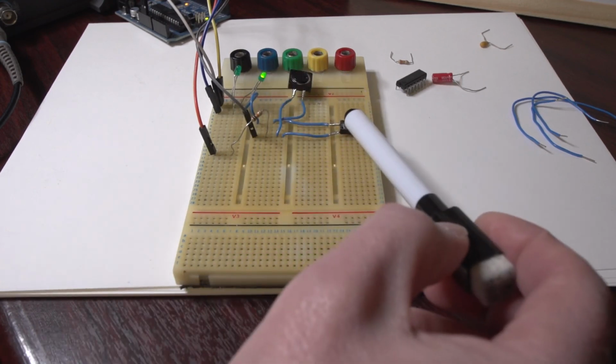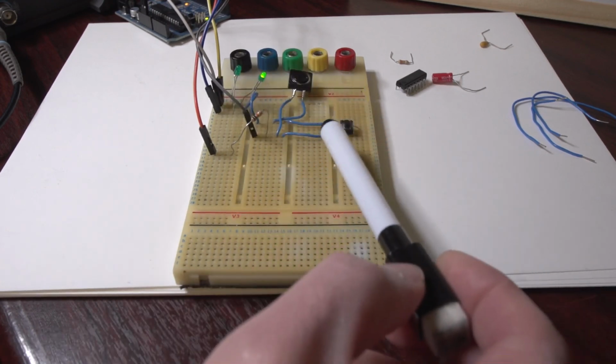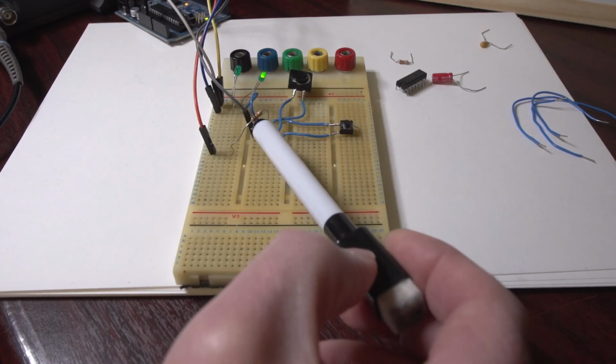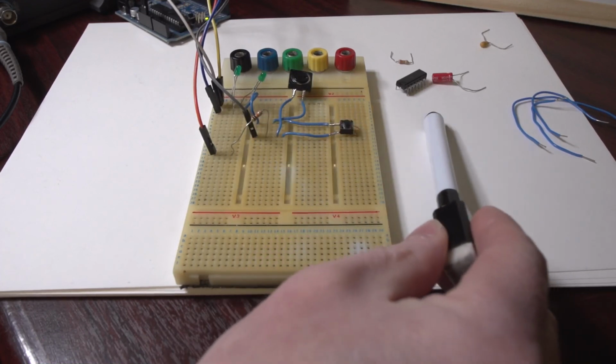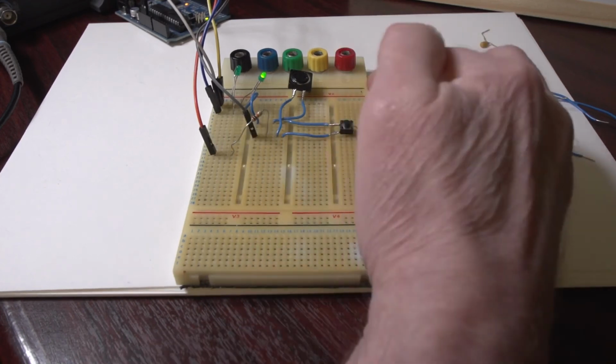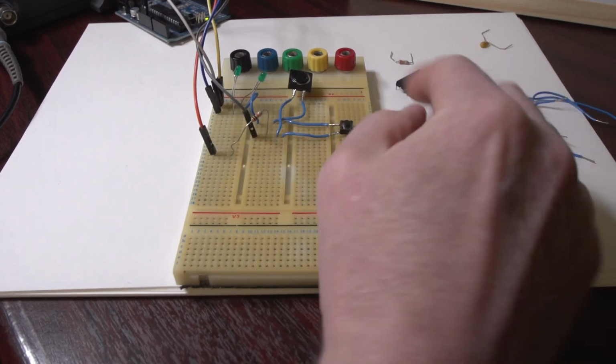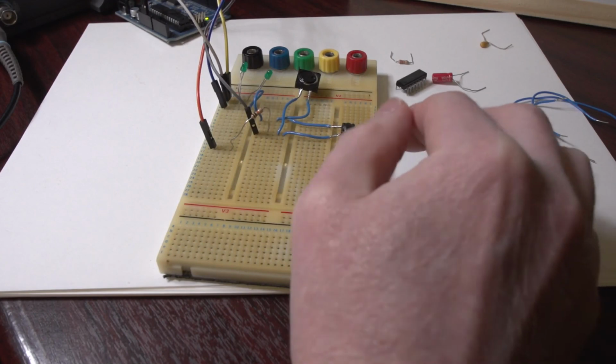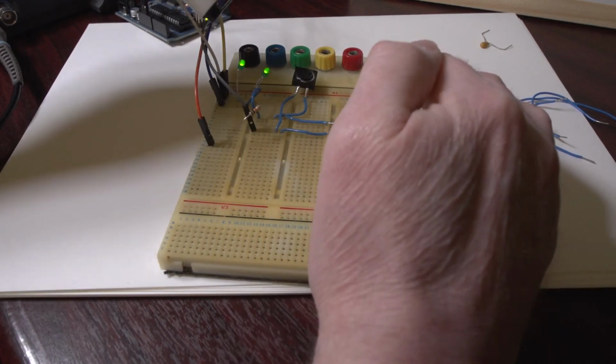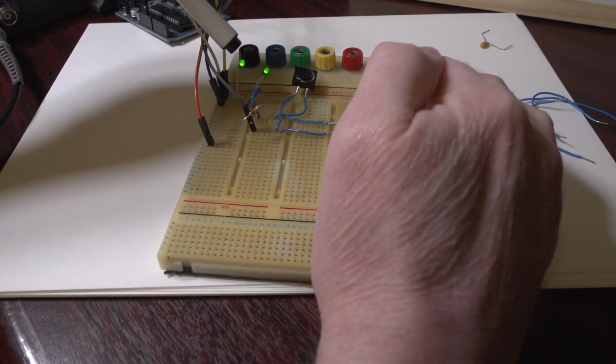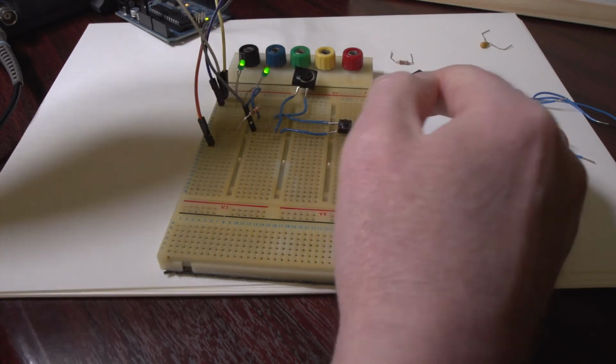The buttons are wired up exactly the same like I said. So really the only component we've got on the buttons now is the 10k pull-up. Everything else is gone. Alright, so we're doing this in software now. Let's come in and press a button and see if this actually works. So here we go, press a button. So now we're in fast mode and the interrupt status LED has gone on. So that's telling us we're in fast mode and it is actually flashing fast.